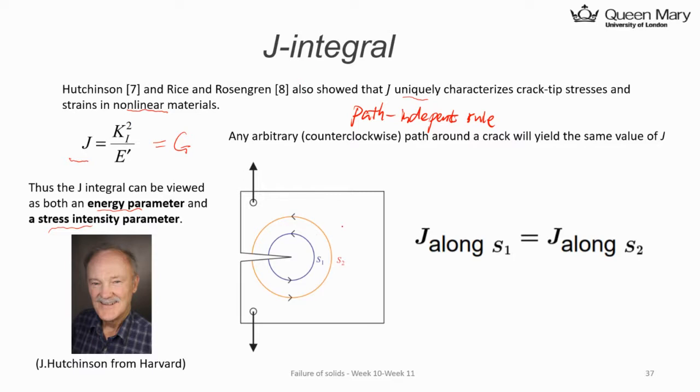So people will ask, if I choose a different contour line, will I get a different answer? The answer is no, you will get the same answer. No matter where you choose your contour line, even a bit closer or a bit further, once you do that line integral, ds, you will get the exact same answer.